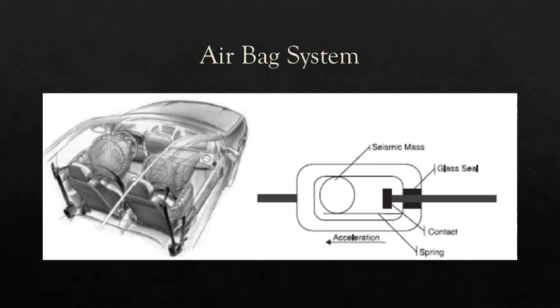These sensors are either mechanical or electrical. The mechanical sensors are of the switching type. The electrical sensors are based on piezoelectric crystal. These sensors are extremely sensitive and are also used to measure impact. Fitted in the front of the car, this sensor closes the contact, which in turn triggers the inflation mechanism. The inflation mechanism is a chemical reaction that generates inert gas to inflate the airbag.